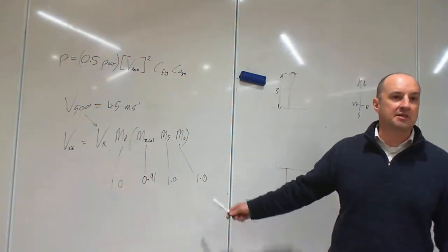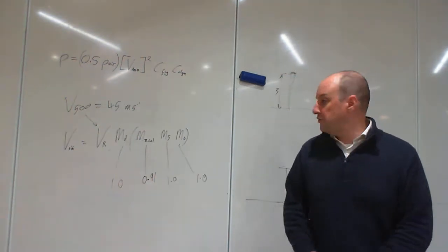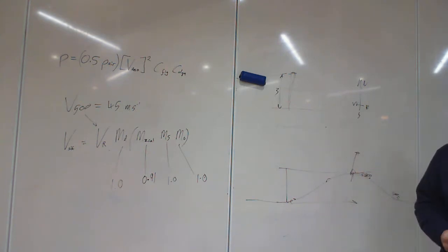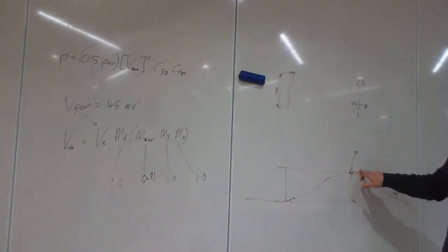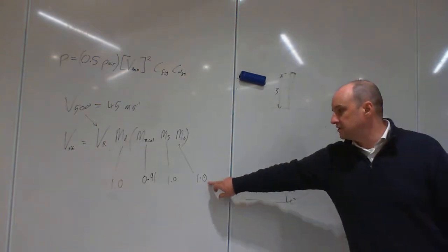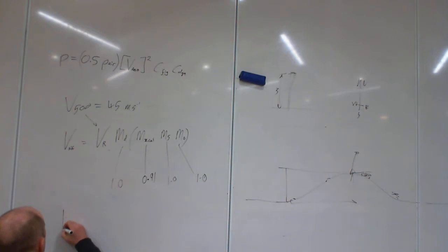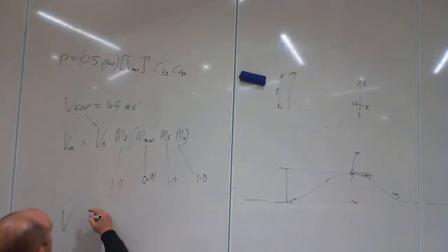I asked Shara, you guys are pretty flat out there. If you built your noise wall on top of a mound of earth, that would increase the wind speed, so you'd have to put something different. If your noise wall is on the ground, which yours is, you can use 1.0. Okay? Therefore, your V, which is your speed, is 45 times 0.91. Can someone put that in their calculator?